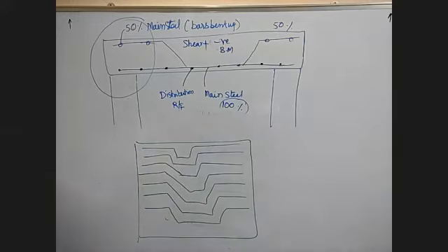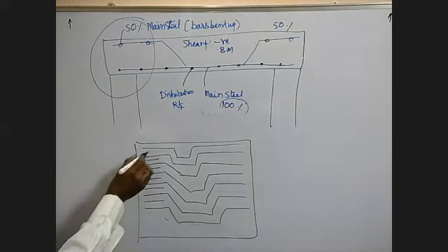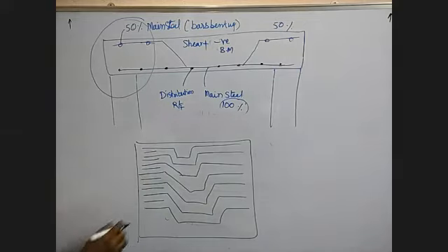Okay, and the additional reinforcement is provided here. Negative bending. We call these negative rods. This is to take care of the negative bending moment at the support. That is all the difference between the slab and the beam. In the beam, we don't provide the negative bars, but we provide the shear reinforcement.